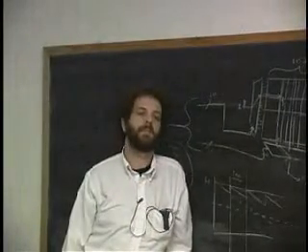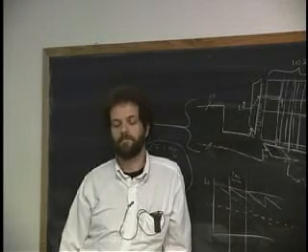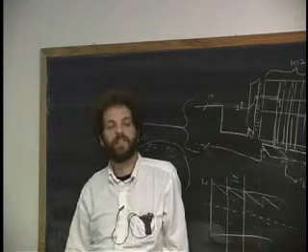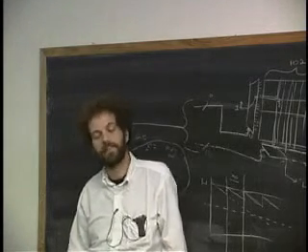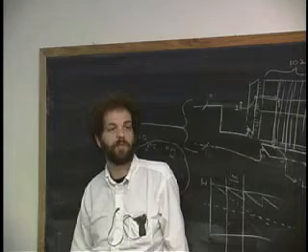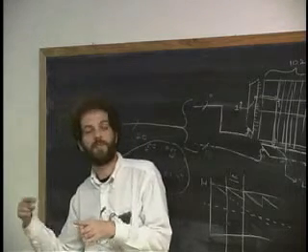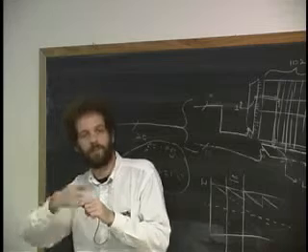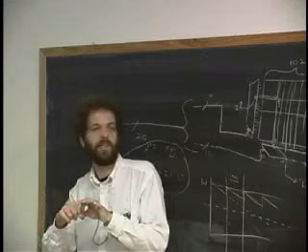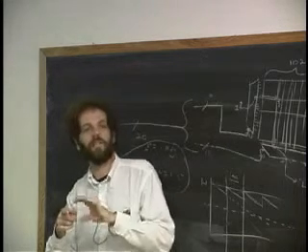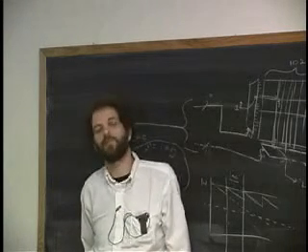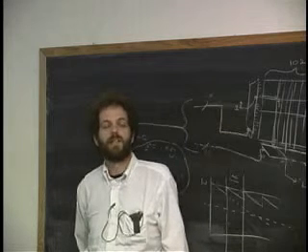Besides capacitors? That's really a great question. There have been a zillion different ways. A lot of them use magnetism of one form or the other. In the old days, of course, there was core memory. You had wires that crossed, and when you put a current through a wire, you get a magnetic field that goes around the wire. You can have a ferrite core, and you can magnetize it one way or the other. Then you can send another wire through and tell whether it was set one way or the other. So that's been done. There have been many different ways tried, but so far this still seems to be the best way that is actually known.